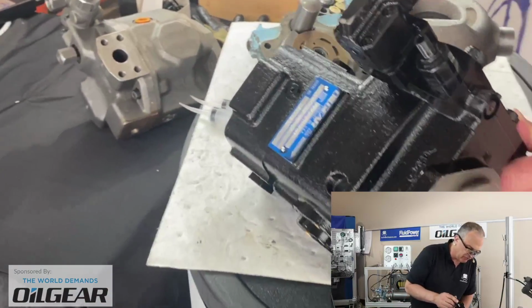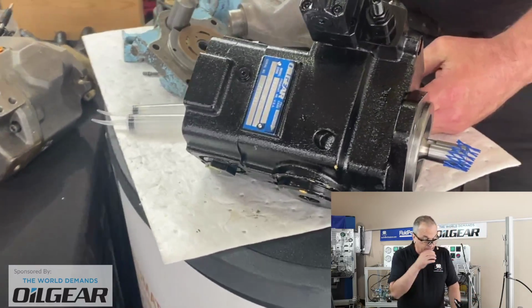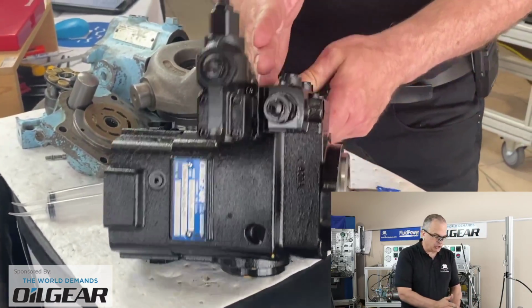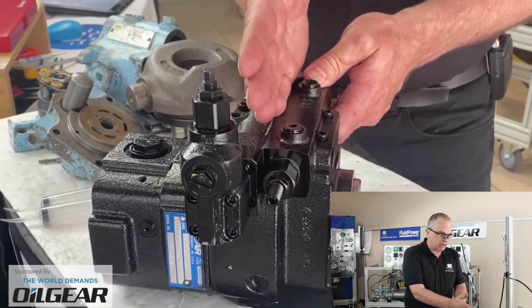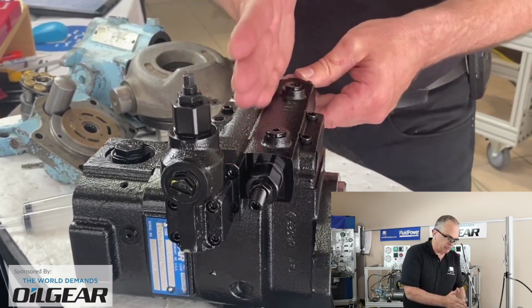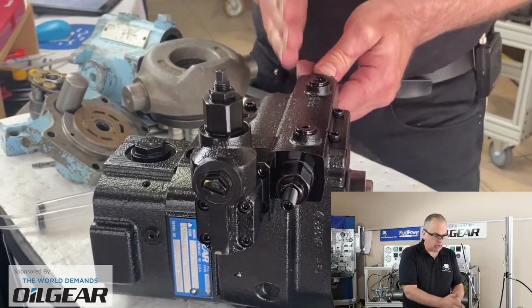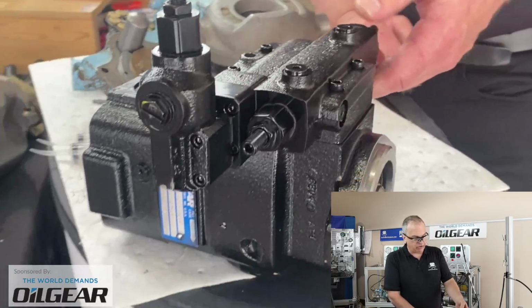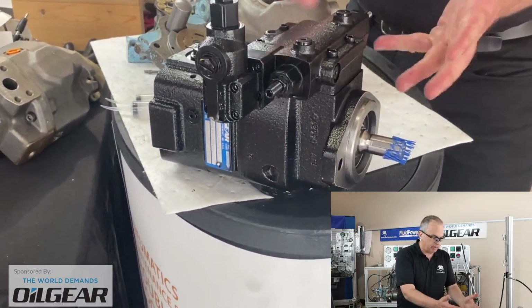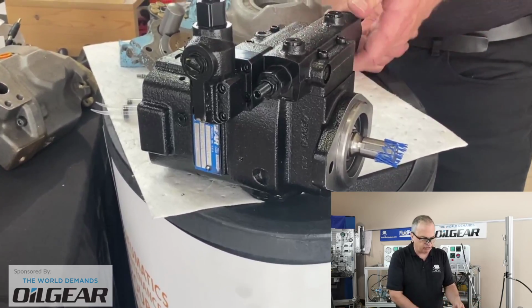A few other pump manufacturers as well have had various pump controllers where the action for angling the swash plate, the control piston, the pressure compensate functions sit at an angle across the case, and that's just another design possibility for getting certain kinds of strength and what have you.